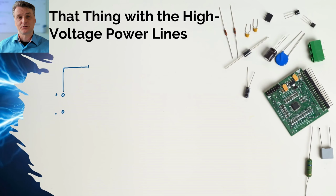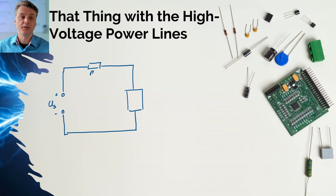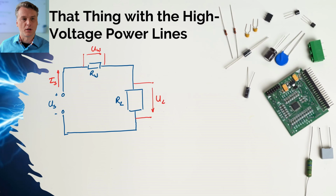Now we can finally talk about the thing with the high voltage power lines, or in general, how to reduce power loss in wires leading up to wherever we want the power to be. Let's draw another circuit, but this time with two resistances. One is the load, where we want power to go, and one is the wire resistance, where we don't want power to go. But wires have a resistance, albeit a small one. We have a supply voltage, and of course there's a supply current going through both of them because they're in a series connection. Both resistors have a voltage drop associated with them, U_W for the wire and U_L for the load.